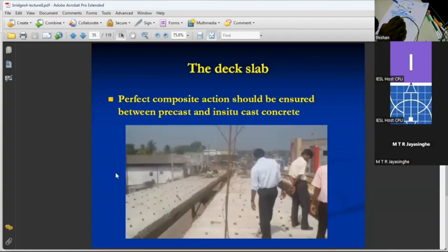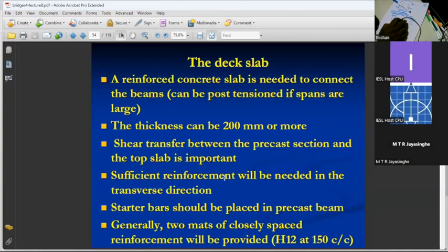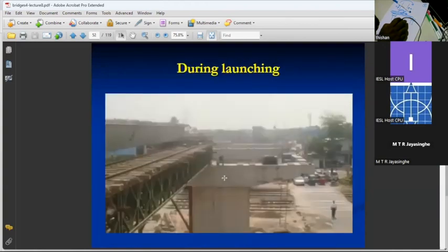And then when all the beams are placed, then the situation becomes very favorable because the loads are now balanced. Whereas during the construction, the loads may not be balanced. So you might find a situation where you are loading only one side of the pier capping beam, and in doing so you are loading only one side of the pier.